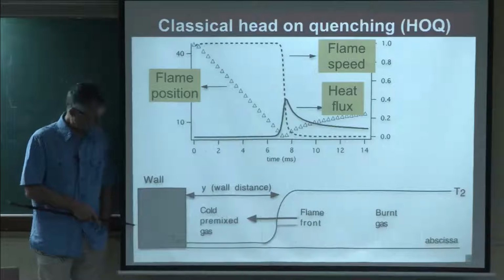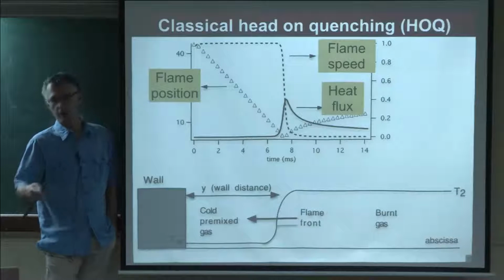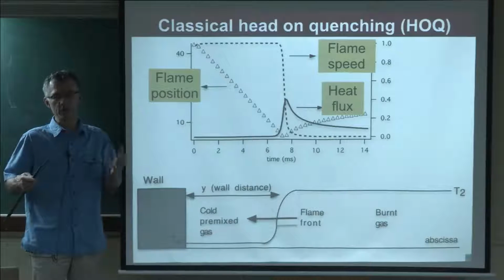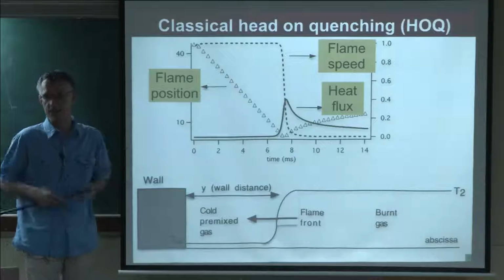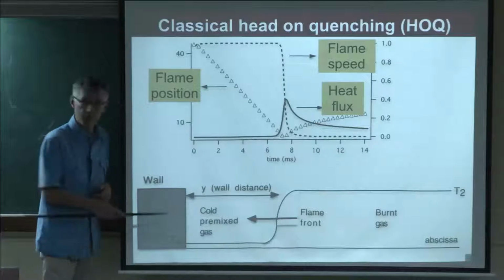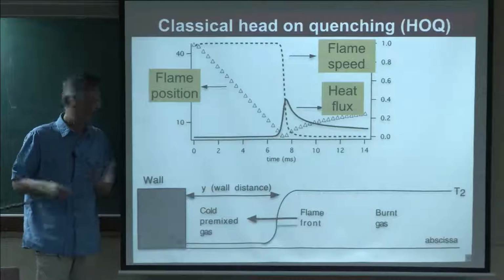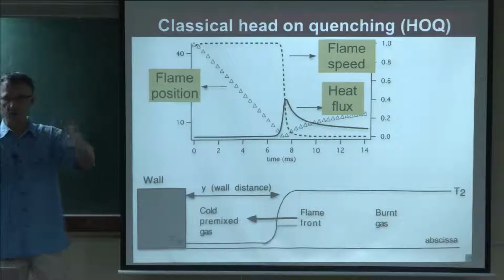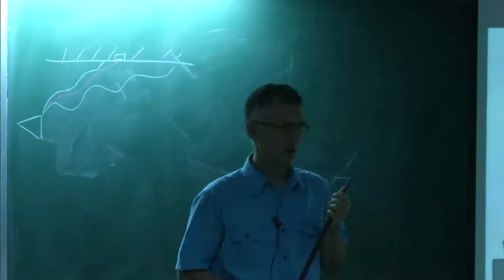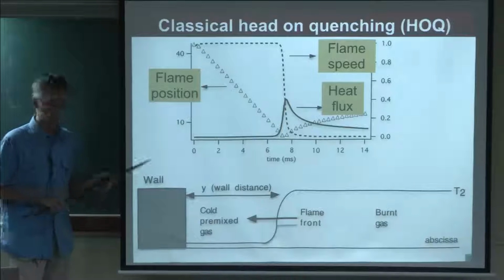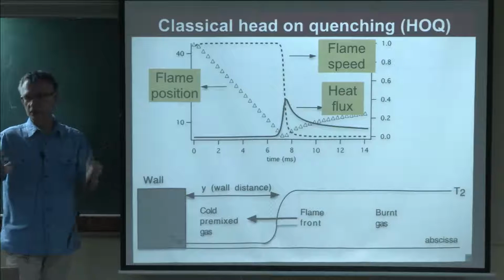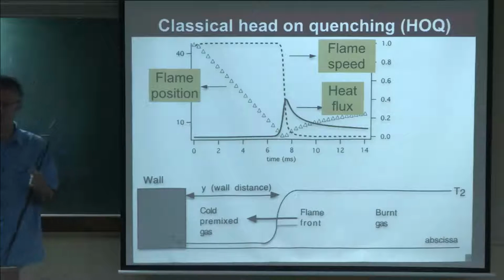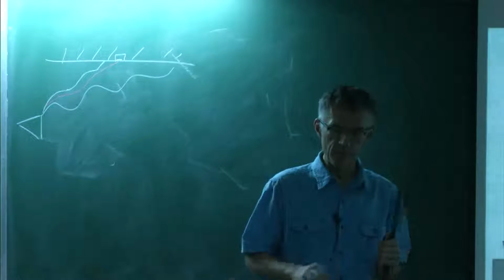Okay, so this cooling water is about 90 degrees, 100. It's under pressure. It can go a little bit more than that, but not much more, because after that you have a problem. So here you have about 90 degrees C. So here you're going to have 200, 250, 150, it depends. Also, the temperature is not homogeneous in the chamber. It has a complicated shape. Designing the cooling systems of an engine is a business in itself. You do computations again, and it's not something I want to discuss today.